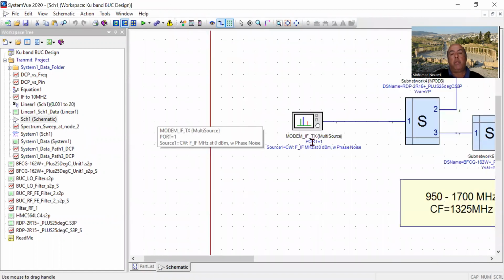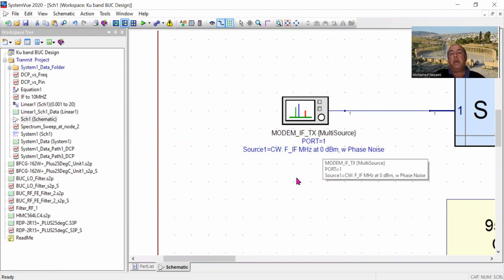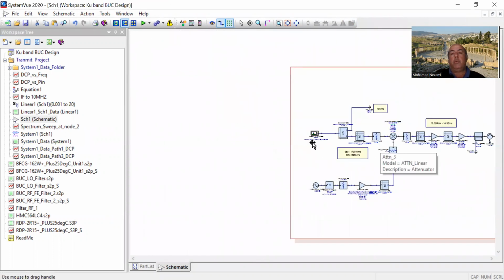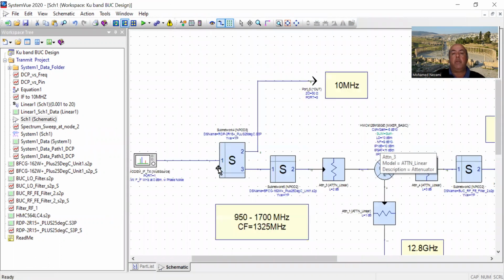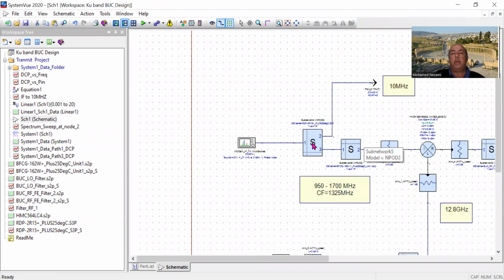So we're starting out with the satellite modem or modulator signal as being 0 dBm, okay, at the IF frequency. So we take that signal and then we have a duplexer that is from Mini-Circuits with this part number. We'll show that in a minute, more details.